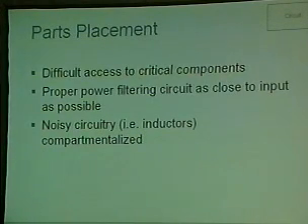Parts placement goes hand in hand with PC board design. You want to make sure that all of your critical components, all of your memory devices, possibly cryptographic processors, are difficult to access. So if you had possibly two boards in your design, you could place all of your critical components in between the two boards and have maybe a tamper response or a tamper sense line somewhere in the connector. So if those two boards were taken apart, you could zeroize memory or do some kind of tamper response.